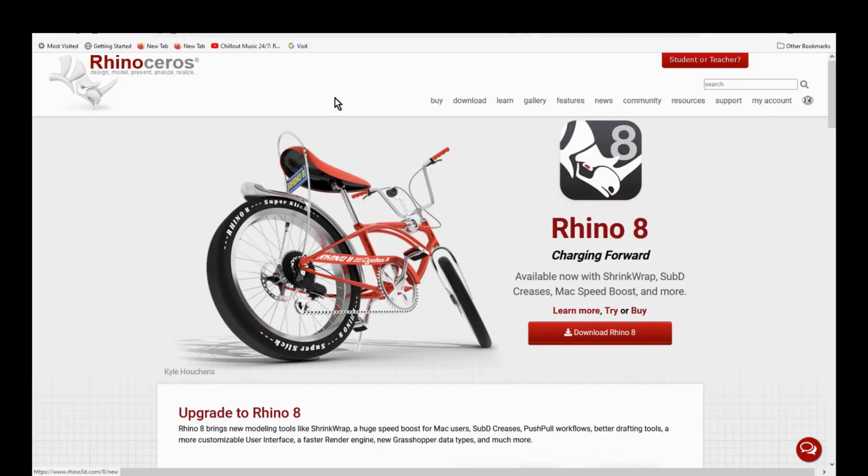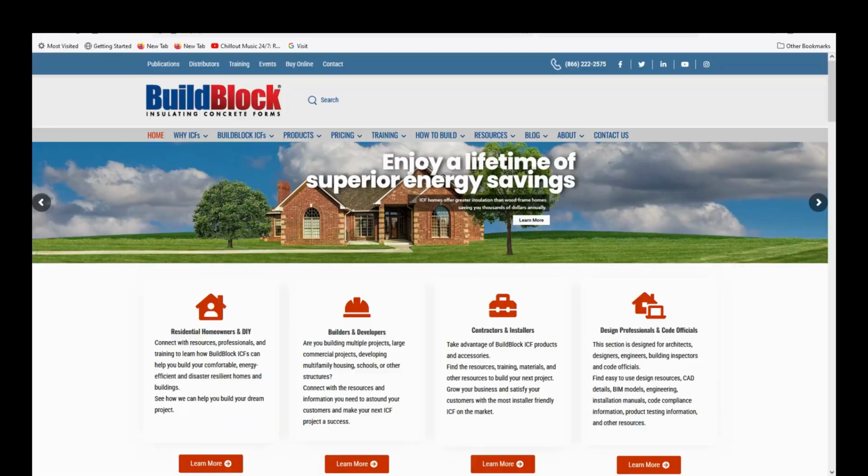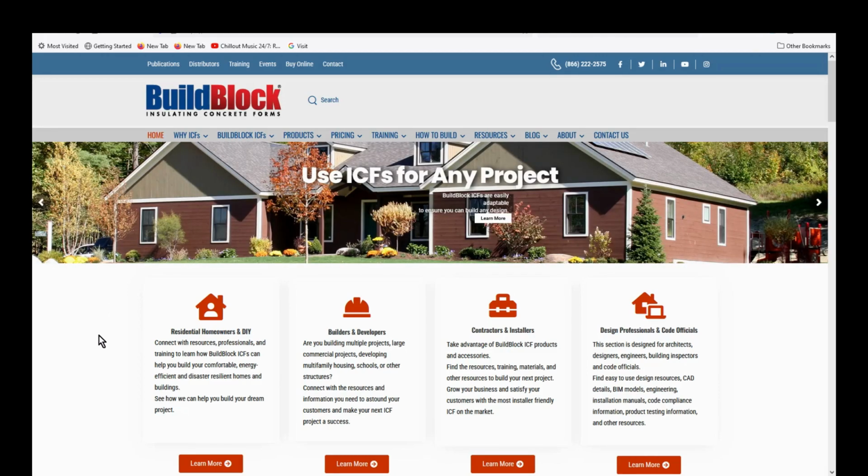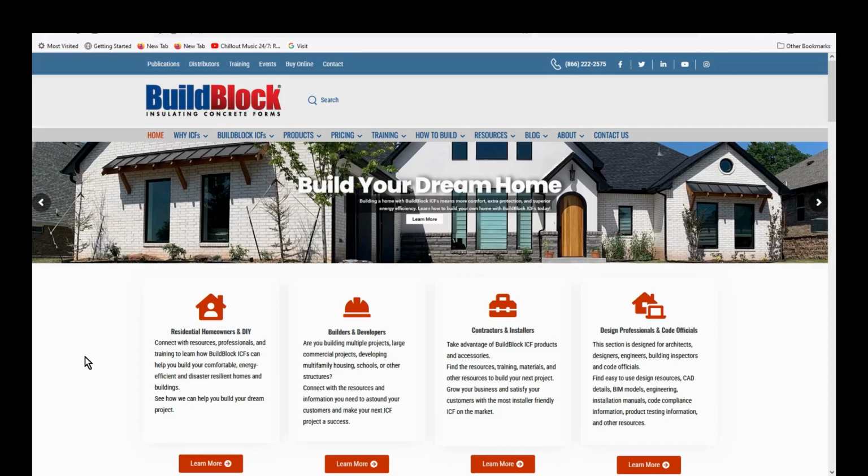Looking at the next thing up is ICF, insulated concrete forms. And we've done projects where we combine cinder blocks with ICF. Usually cinder blocks are more on the foundational parts, columns, exterior features. And then the ICF is there for, of course, insulation. And with the wind loads, it's there for mass. You can get a lot more mass out of it for the dollar.